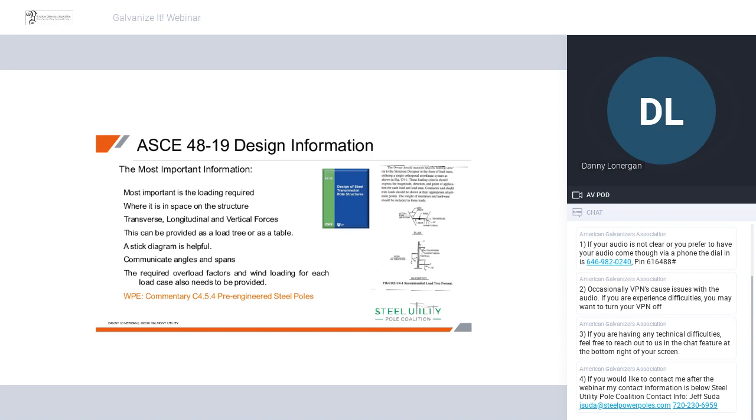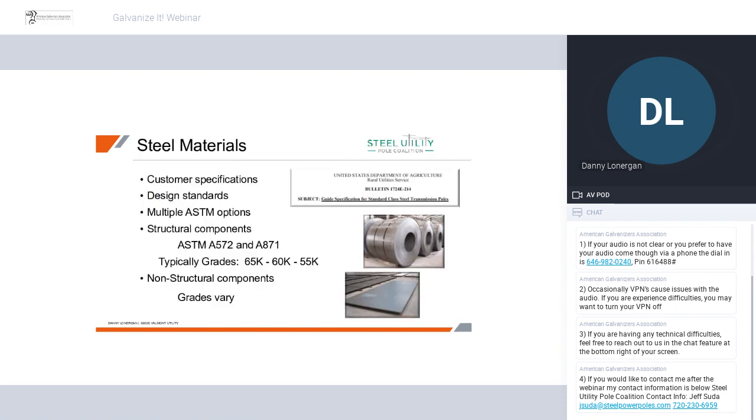Another very important topic is foundations. They make reference to the foundation needing to be understood, studied, and concluded. So it's not an automatic 10% plus 2, and we'll talk about that in a couple slides. So 4811 does a lot. It really drives our industry for a steel structure, and most importantly, it gives great guidance to pre-engineered structures.